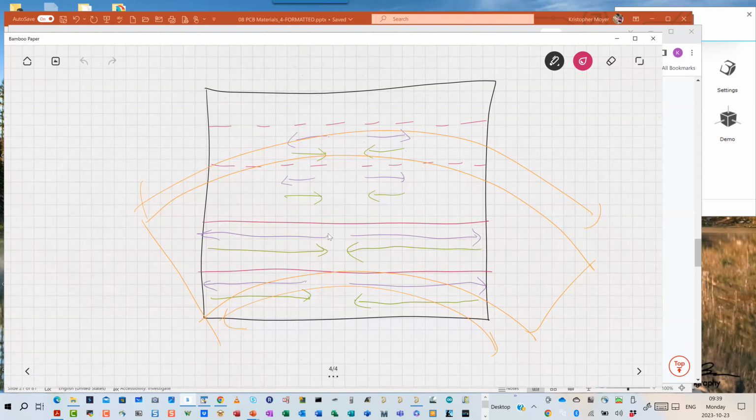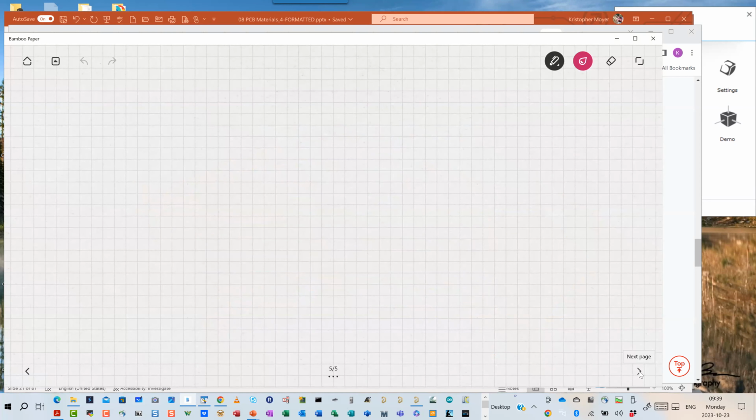That's at least what's in IPC. Now, different military aerospace standards, like US DoD or the European Space Agency or whoever, might have their own. But from IPC's point of view, it says when not indicated on the master drawing, minimum dielectric thickness shall be, and I believe it's 3.9 mils because it works out to the metric equivalent converted.